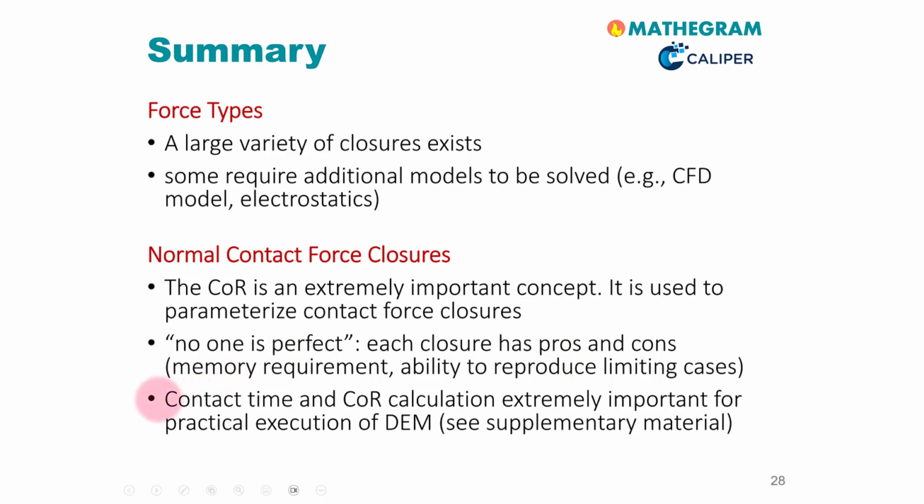In order to choose the correct time step, it's very important that you are able to calculate the contact time and the coefficient of restitution for your normal contact force closure. This is of extremely high practical relevance for conducting DEM-based simulations. In a supplementary material you find more details about this and how you can do these calculations.